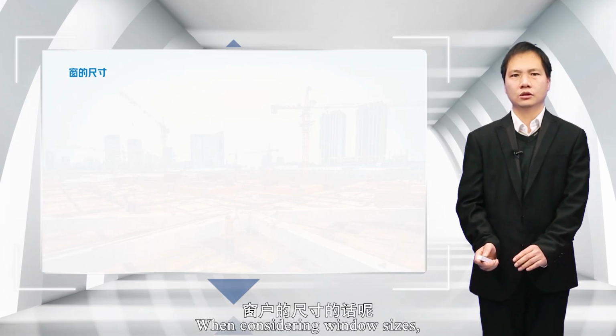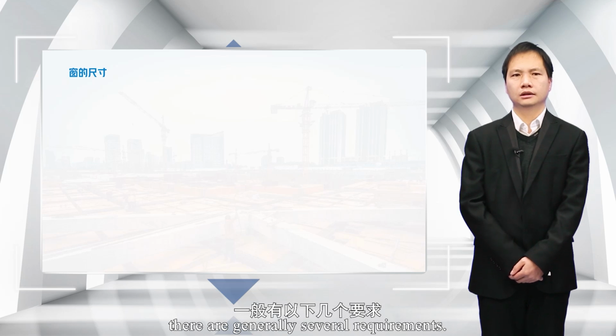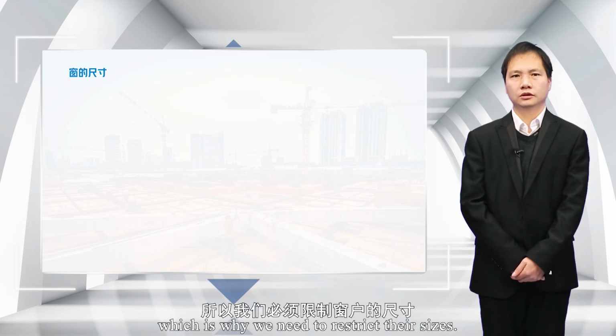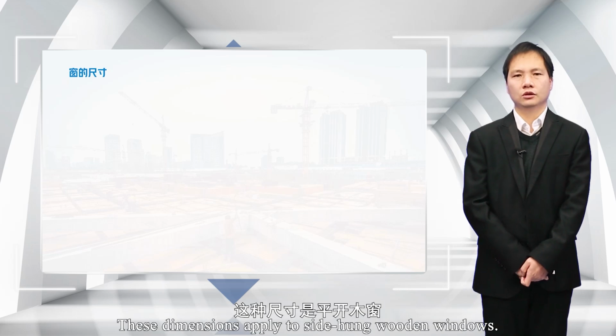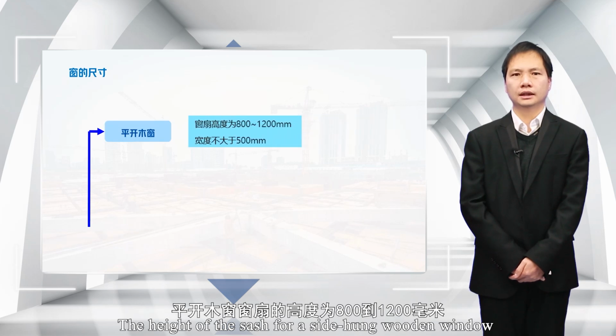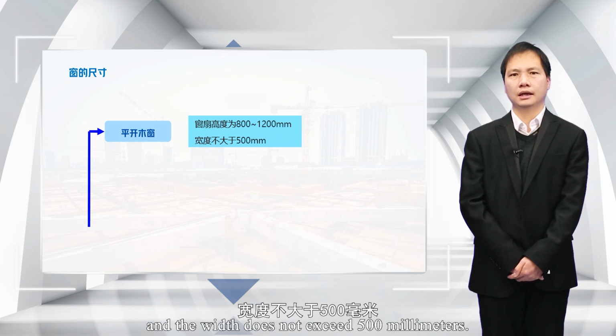Now, let's talk about the dimensions of windows. When considering window sizes, there are generally several requirements. The main requirement is that they must be sturdy and durable, which is why we need to restrict their sizes. These dimensions apply to side-hung wooden windows. The height of the sash for a side-hung wooden window ranges from 800 to 1,200 millimeters, and the width does not exceed 500 millimeters.